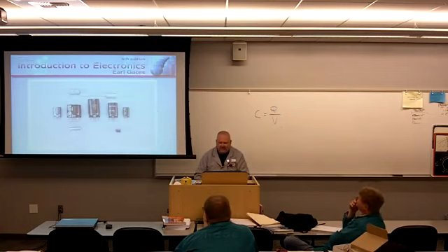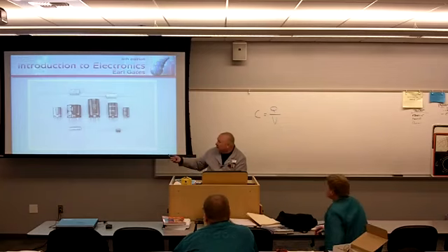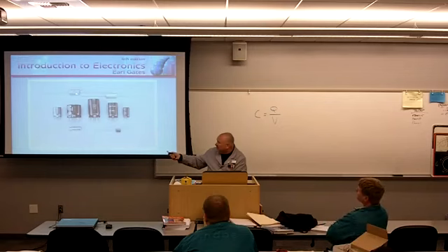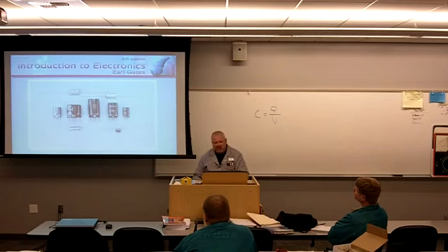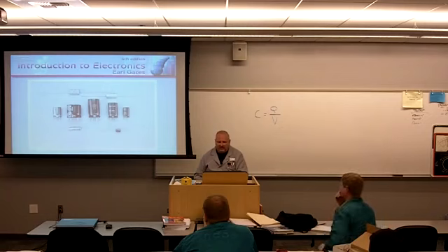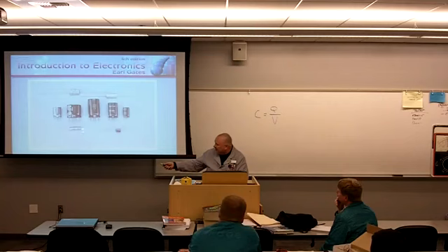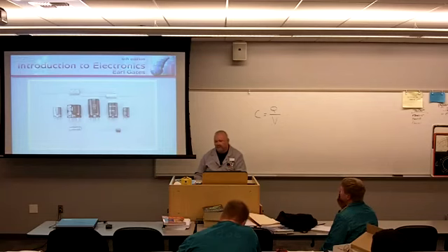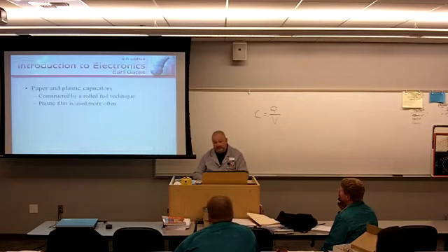But it's my personal collection of capacitors. These are all electrolytic capacitors. On the electrolytic capacitors, you've got to look for the markings to find which lead is the negative lead and which one's the positive lead. There will be some discerning mark on it. Some manufacturers identify the negative lead, some identify the positive lead. You just got to pay particular attention. This one, with the band on it, would signify the negative lead. See that solid band? You just got to look and be observant. Put it in backwards, it will explode.